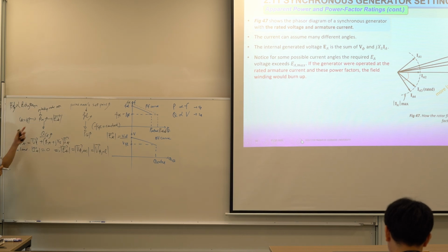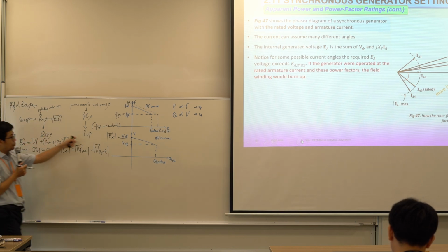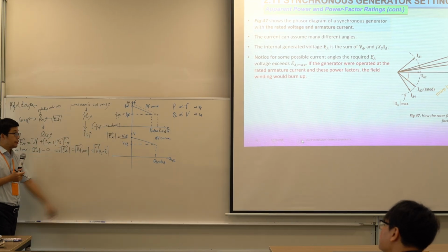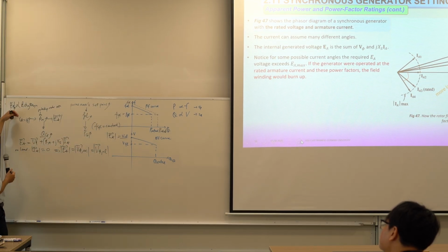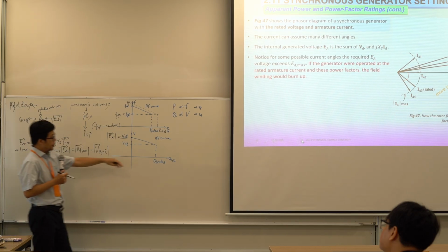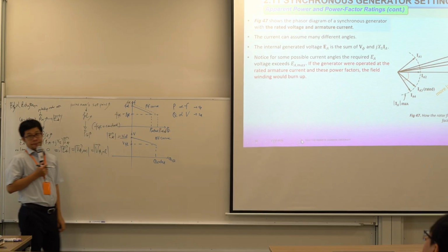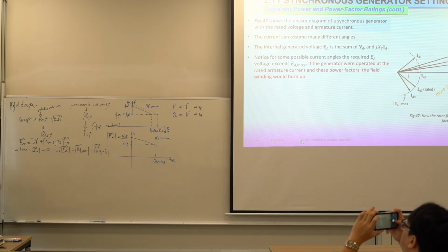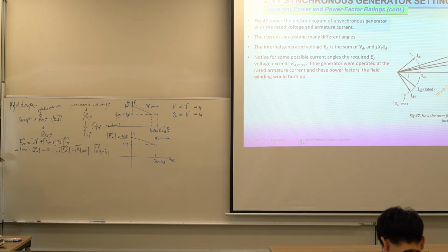So that means when we increase EA, we increase reactive power, otherwise reduce EA by reducing IF, and Q rated is reduced. So last Friday we discussed this information, right? Now continue.